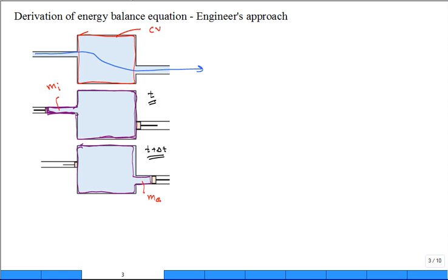So for conservation of mass, what we say is the amount that is our focus of our study, our closed system, which is deforming, our closed system is the mass at time t plus delta t is equal to the mass at time t. Well, the mass at time t plus delta t is made up of two parts.